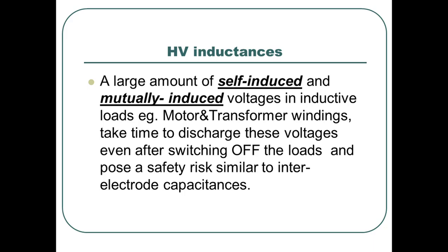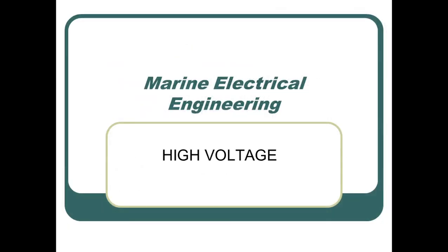When we speak about high voltage inductance, a large amount of self-induced and mutually induced voltage in the inductive load, for example motor and transformer winding, takes time to discharge even after switching off the load and poses a safety risk similar to inter-electrode capacitance. Okay.